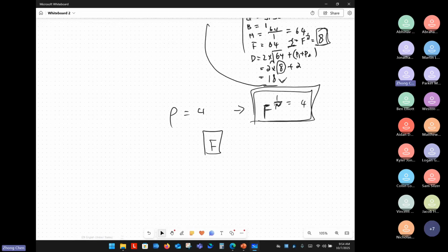Okay, so let me say it again. The conclusion we drew before, with the very complicated, very generic equations, is that if we keep rho equal to 4, the delay time will be the minimum. So if we try to make the best stage effort equal to 4, I will always achieve the best delay time.